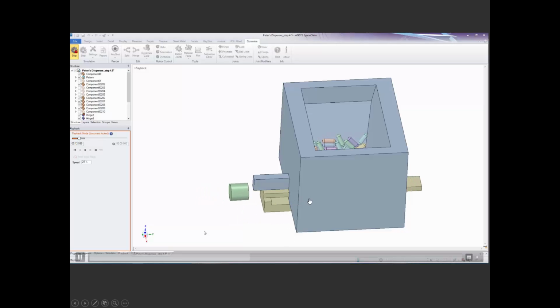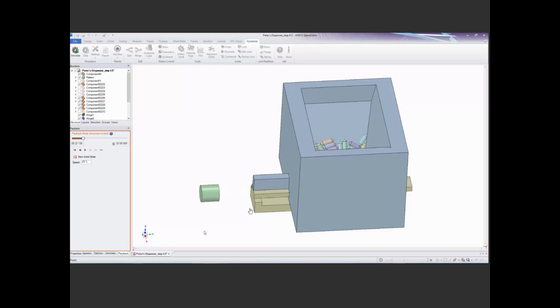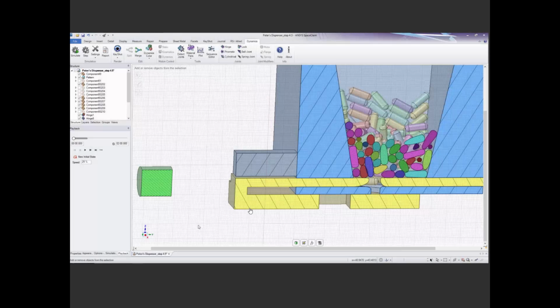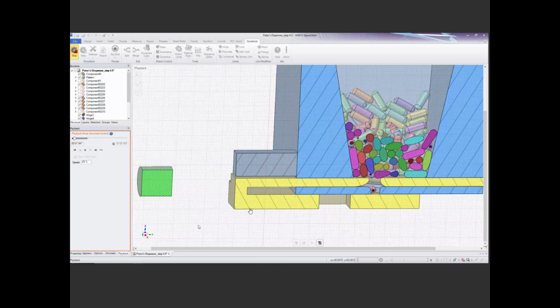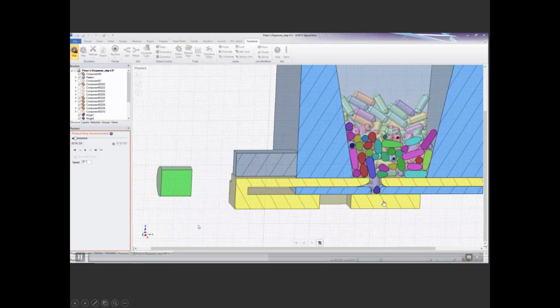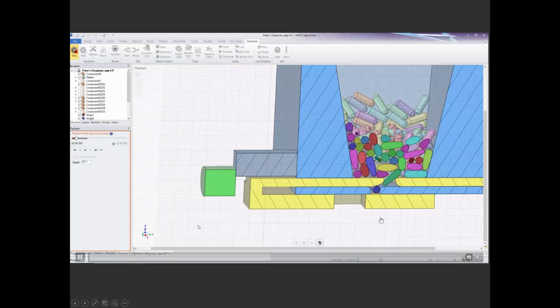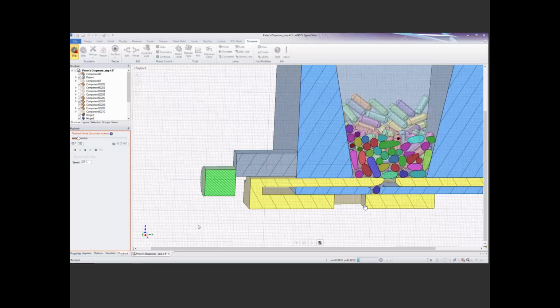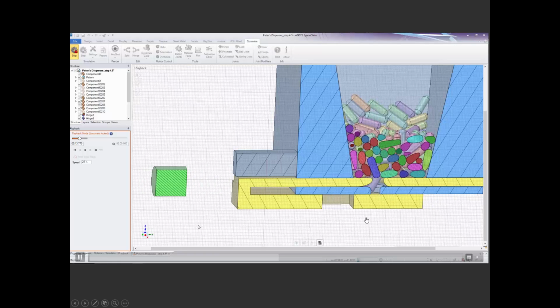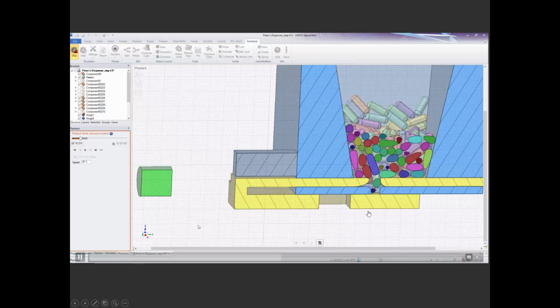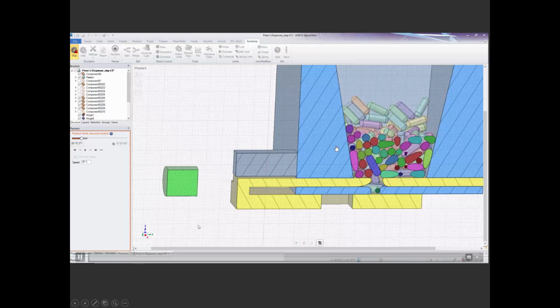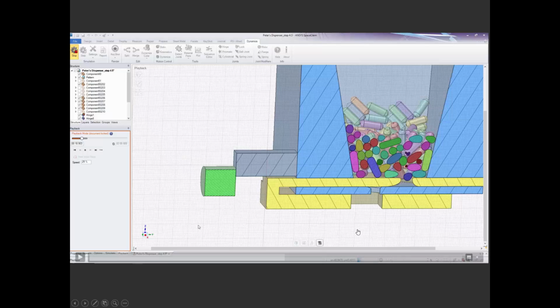So it looks like this. We have a slider that runs back and forth, and on the left-hand side we have a push-button mechanism that is designed in such a way that it prevents the pills from being damaged in this process. It sets a limit as to how hard you can push against the pills if they get stuck in the wrong place like that. And it happens all the time at this stage in the process, and clearly this is a bit of an engineering blunder.